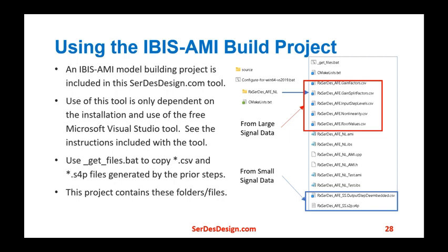Using the IBIS-AMI model building project. An IBIS-AMI model building project is included in this receiver AFE nonlinear modeling tool. Use of this tool is only dependent on the installation and use of the free Microsoft Visual Studio tool. See the instructions included with the tool.